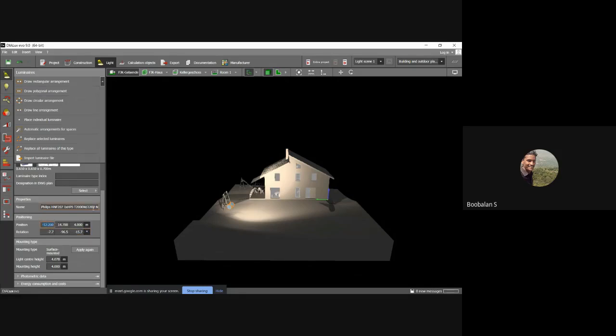-12 is coming. With the help of a numeric number, you can adjust your lighting system. So here the default is -12. So without mouse operation, you can change it here. So I'm just going to give you -10, where the lighting system is going to be moving towards my building. So you can have -5, even closer to my building. So -15, even it should be longer than my building. The same way, if I change my second light, you can do -15.